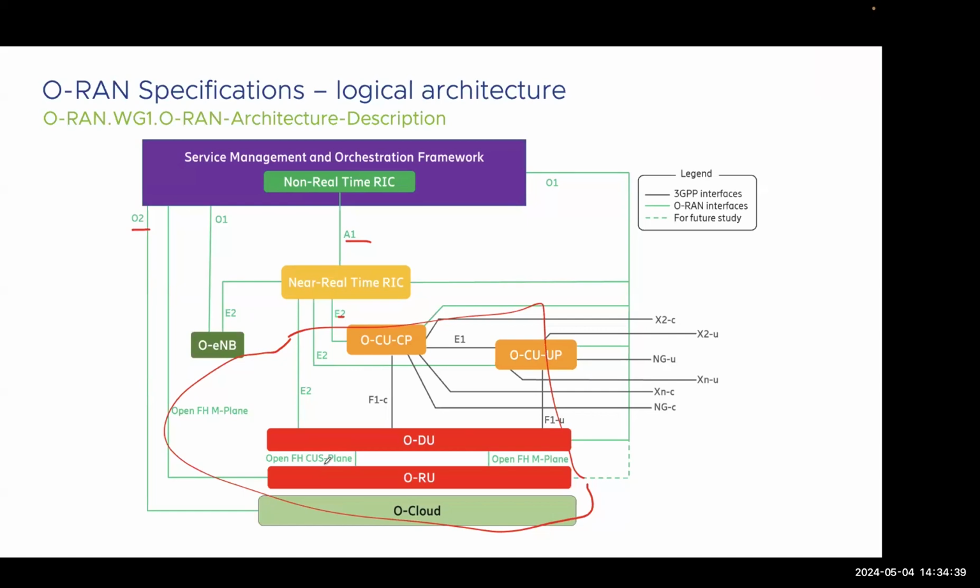Okay, it's a good question, and here is how it moved. First, most of 4G and a few parts of 5G use CPRI, not eCPRI, and CPRI is completely closed and static. Then what happened with 5G massive MIMO? The communication between the baseband unit and the radio unit, this fronthaul, became huge. We're speaking about several gigabits, and in 64T64R massive MIMO it can reach a couple of hundred gigabits per second. So one way to optimize that was to use the eCPRI protocol.